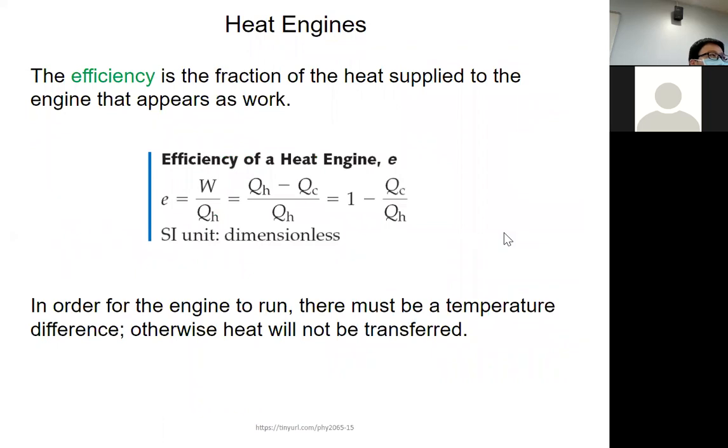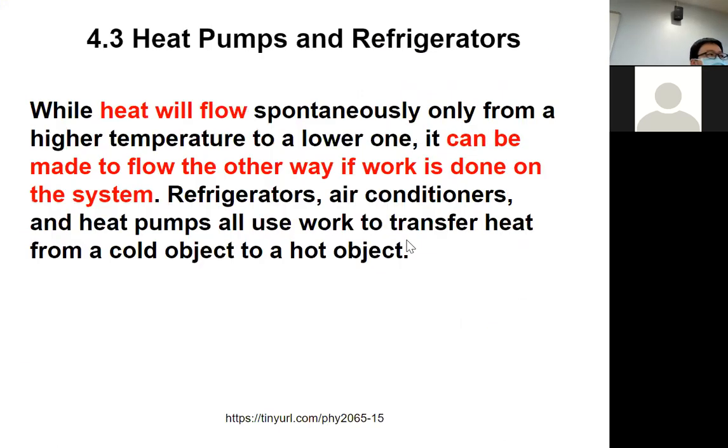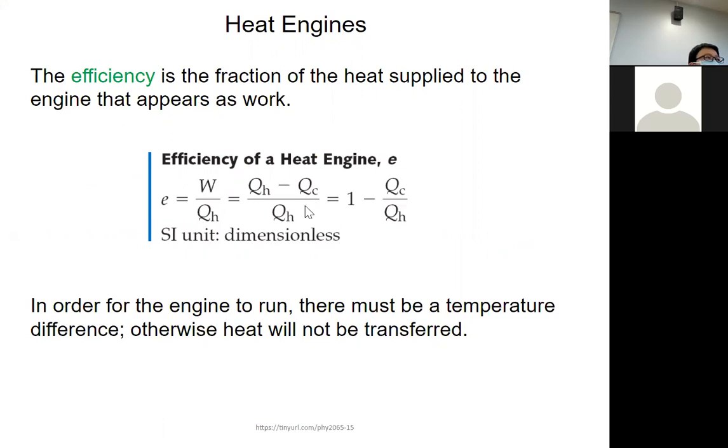The efficiency of the engine is defined by how much work can be done divided by the heat it takes in, so W over QH. And W is equal to QH minus QC, so you can write this expression as 1 minus QC over QH. So there are several different expressions you can use.